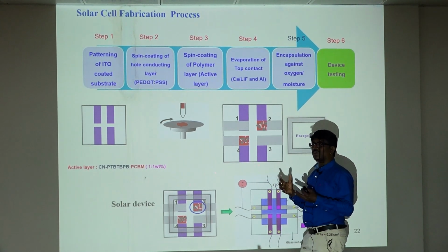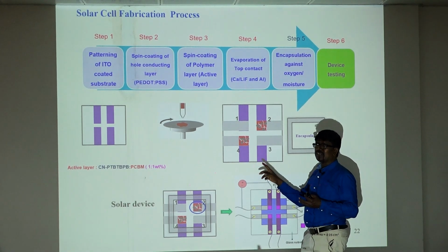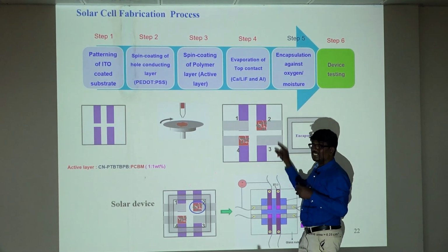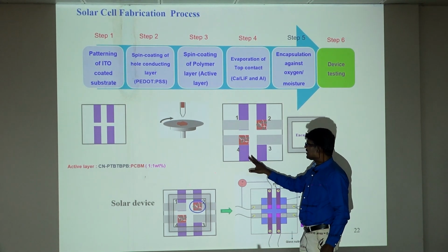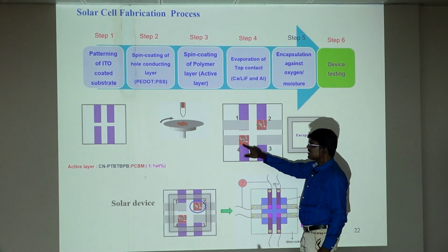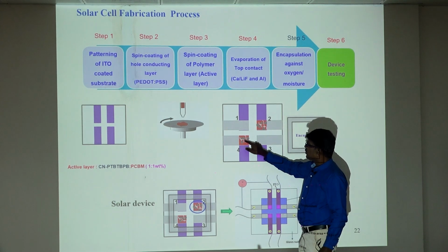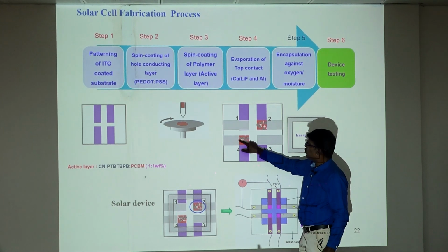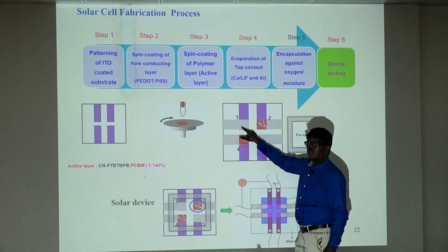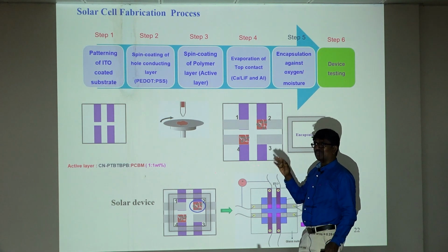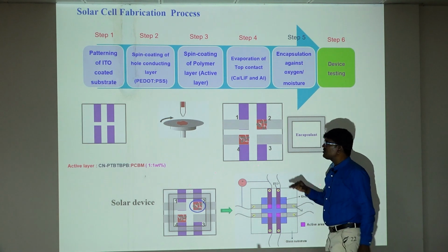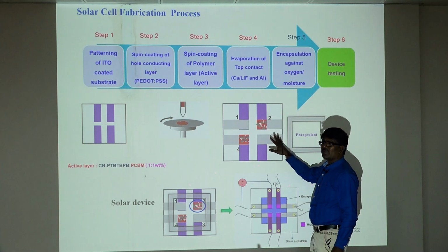So that's the UV etching. It takes at least 3 days for this size of glass plate. So once you UV etch this one, it becomes non-connecting and connecting. On the connecting side, you go to spin coating. You do layer by layer of this material, coating only in this area, the 4 cells. Then wipe it out, we clean. Once we clean this one, we do all the fabrication.